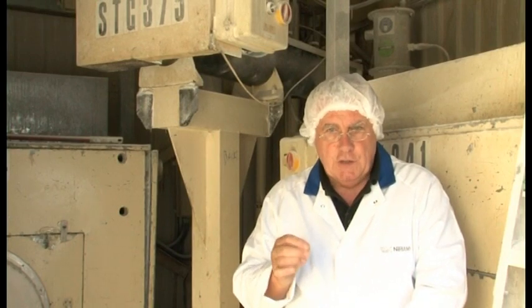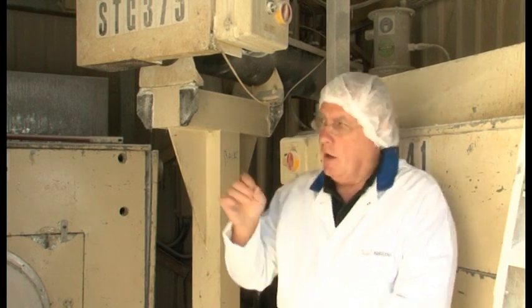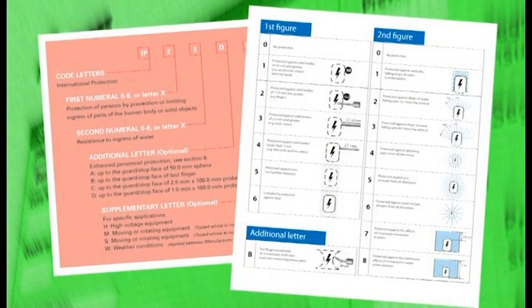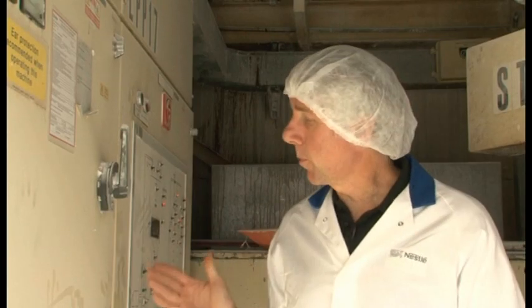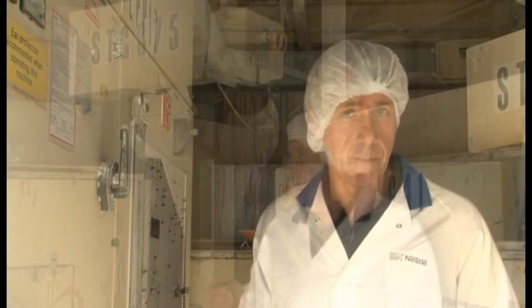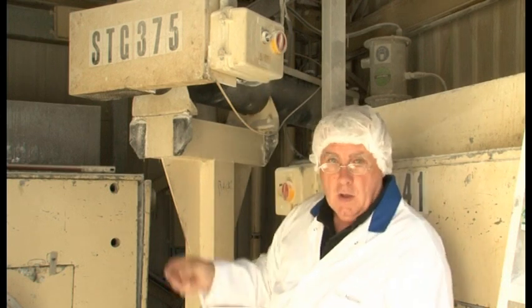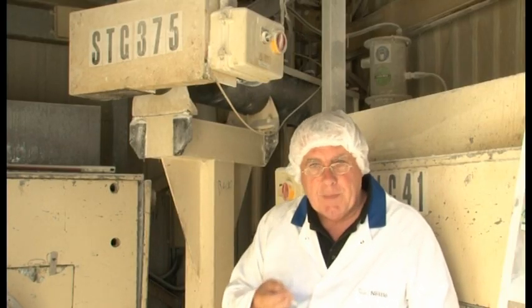Secondly, barriers or enclosures need to provide suitable protection for persons against contact with hazardous parts inside the enclosure. In order to confirm that the necessary level of protection has been afforded, knowledge of IP and similar codes will be necessary. For example, it's generally considered that the minimum level of protection required to prevent fingers touching enclosed live parts can be provided by IP2X or IPXXB equipment, with certain exceptions. The trouble is that unless you have the official British standard test finger with you, the suitability of IP ratings is hard to guarantee. So we have to take a common sense approach.